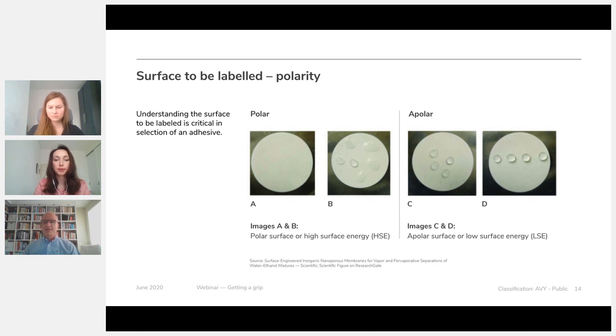And you may recognize this picture because it is basically what you have when you have freshly waxed your car. The wax is very apolar and it makes the surface repellent to the water, and therefore the water is unable to wet onto the surface and it can just flow away from your freshly shined car. This may be what you want for a car, but it clearly is not what we want for an adhesive.